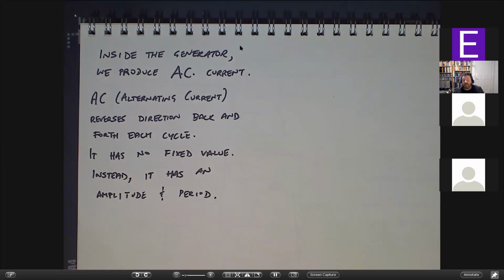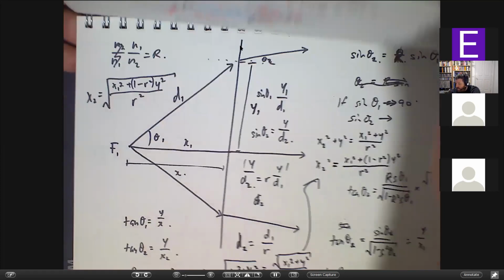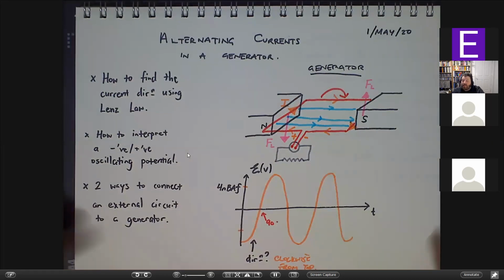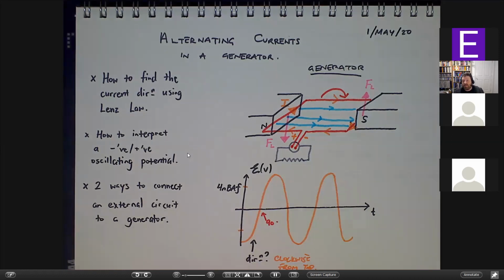So if you think about V equals IR, V equals IR starts to become not so true once we talk about alternating currents, but for the moment, let's imagine it is. The current and the voltage are just linear relationships to one another. You just multiply by R. So if the graph of voltage looks like this, then the graph of current is just going to look like that divided by R. So that means we can no longer just say, oh, it's 3 amps of current. We have to say the maximum current is whatever that is, the amplitude, and it's oscillating with a particular period.